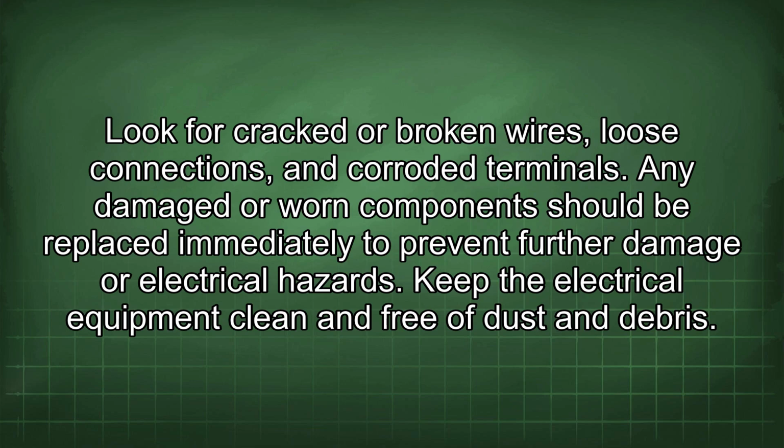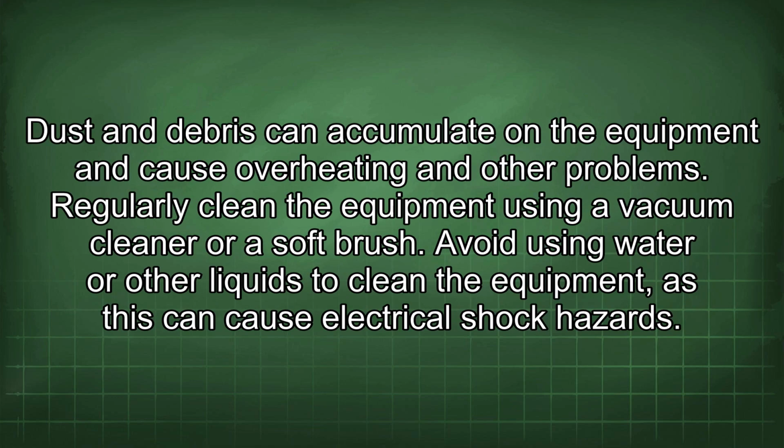Keep the electrical equipment clean and free of dust and debris. Dust and debris can accumulate in the equipment and cause overheating and other problems. Regularly clean the equipment using a vacuum cleaner or a soft brush. Avoid using water or other liquids to clean the equipment, as this can cause electrical shock hazards.